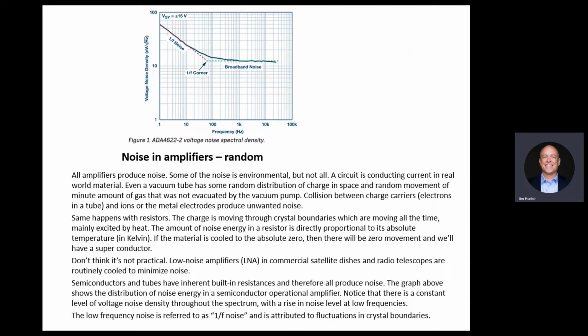Well, not always. There are limits to what you can do. If you have a lot of amplification from a device and it's very linear, that's fine. If it's not very linear, then you start to reduce that amplification. So you're playing the game, exactly. And there are other issues that we didn't touch on. In addition to the voltage noise I show here, there's also current noise. The higher the current you run in a device, the more noise you're going to get. So you get the combination of the two, and you start adjusting.